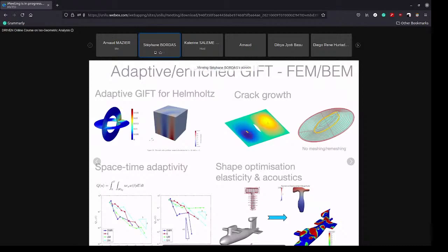You can start directly from the CAD model. I can show you a demonstration because we have a code which is quasi-commercial to do this, developed by Haojie Lian. And so basically what you do is you start with the NURBS control points, you solve, and you never at any point generate any mesh. So there is no mesh. It all directly comes from the control points. This is a really beautiful application of the idea of isogeometric analysis, because there is no parameterization of the volume, which is one of the difficulties.